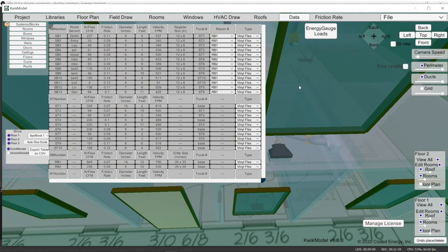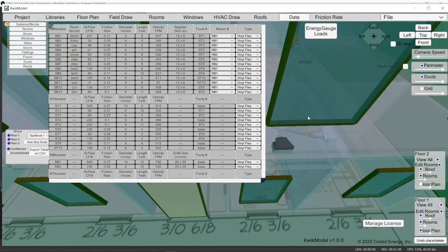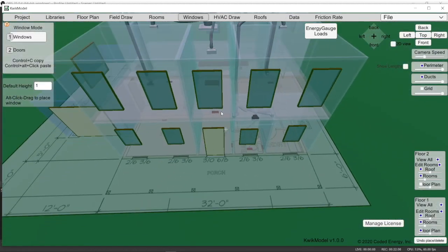You know, you're gonna then kind of go back, check all your work. Then you're gonna maybe talk to the builder, talk to the HVAC subcontractor, find out what brand of equipment they want to use, look up some actual pieces of equipment, plug those numbers in, fine tune it, come back. You always want to go back and recalculate your loads at the very end. You always want to come back and resize your ducts at the very end. Let's go back and take a look at this.